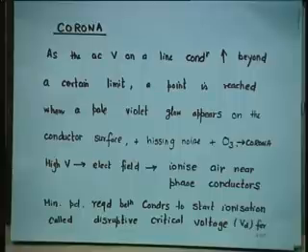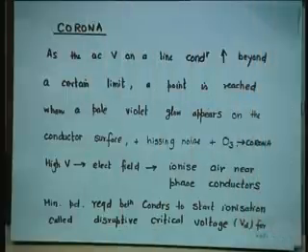And the story doesn't end there. There is ozone also coming along with it. So, it is a 3-pronged attack on a conductor. There is a glow, there is a noise, and there is a gas formation, which is ozone, O3. High voltage will always have an electric field. This electric field, what does it do? It ionizes air near the phase conductor.